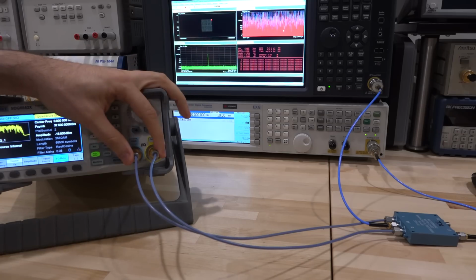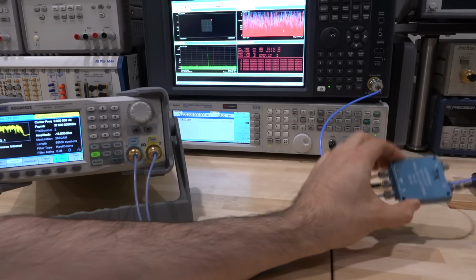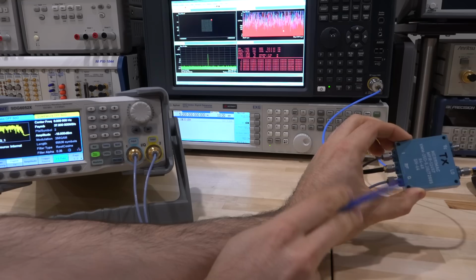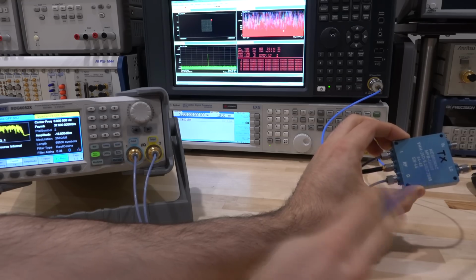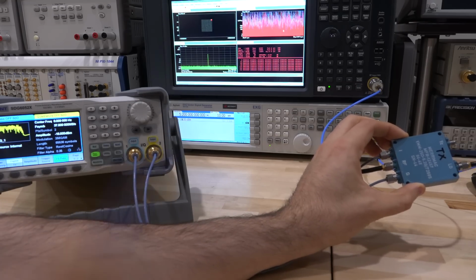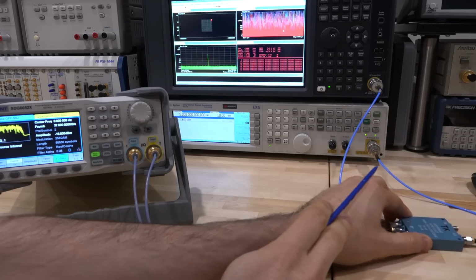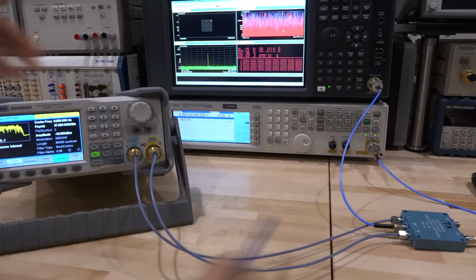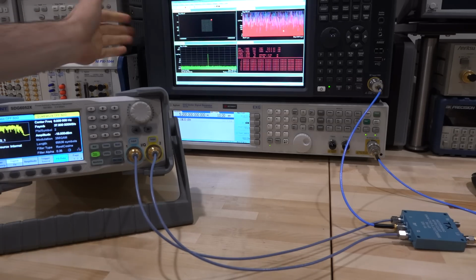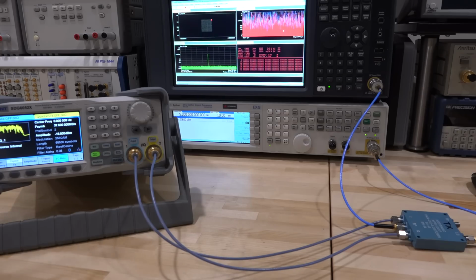So I'm connecting channel I and Q to the input of this modulator right here. So it accepts I and Q, and I'm applying an LO signal to it, which is coming from my Agilent EXG, and the RF output is taken directly and applied to the Keysight MXA. So we should be able to see the modulation directly, and I'm going to zoom onto the screen of the spectrum analyzer so we can see it. Everything, the settings that you saw, I haven't changed anything yet, so we're going to be able to see the quality of the constellation and moving the center frequency around, and we can see the impact on the constellation that we see on the spectrum analyzer.